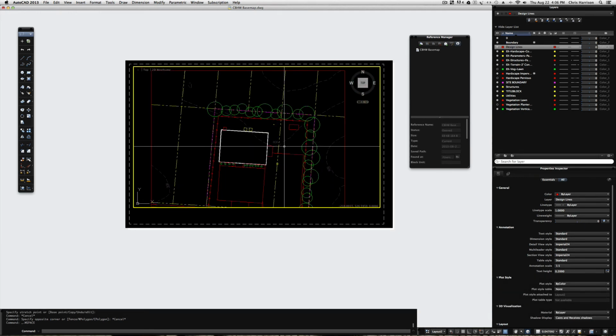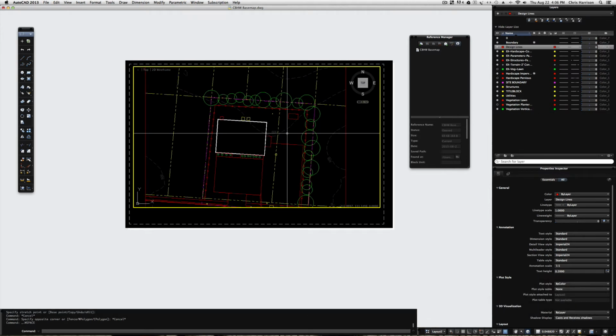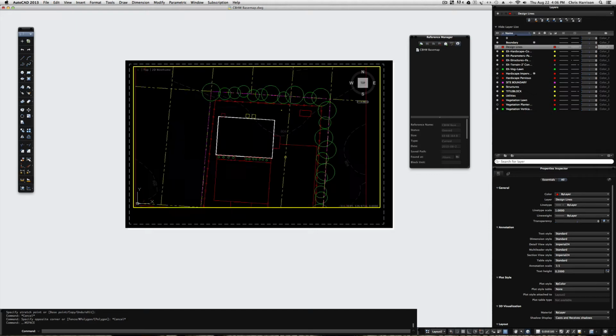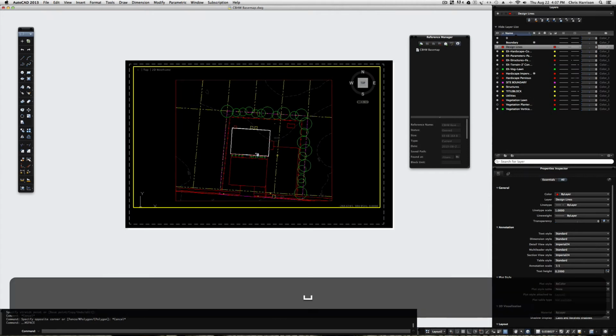So now what we want to do is to scale this thing. And the scaling is just allocating an inch increment to a foot increment, or a ratio, and that's what we're going to scale it at, a 1 to 20, like we set the line type scale to. And you want to do that just by being in your model space.